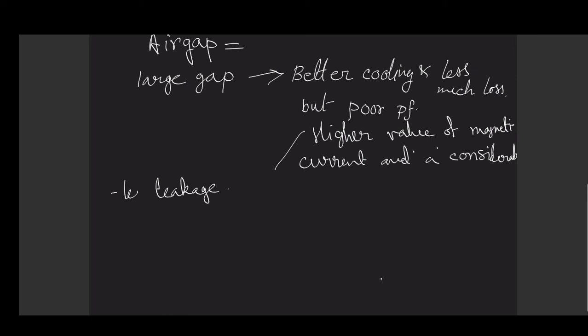Now, if you consider that if you reduce the air gap, then your machine torque profile will be enhanced.